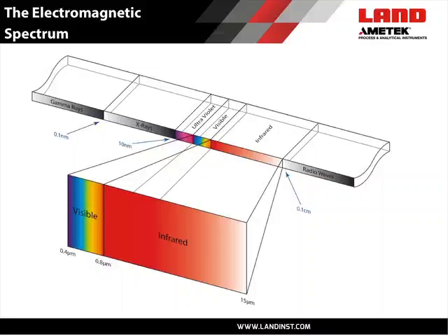Non-contact radiation thermometers and thermal imagers are designed to respond to wavelengths within the visible and the infrared portions of the electromagnetic spectrum. In practice, these thermometers typically operate over portions of the spectrum between about 0.5 out to 14 micrometers.